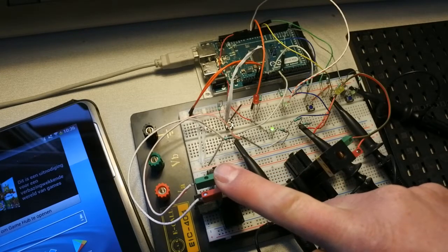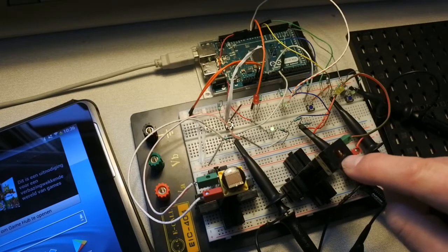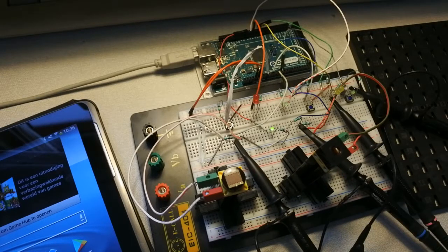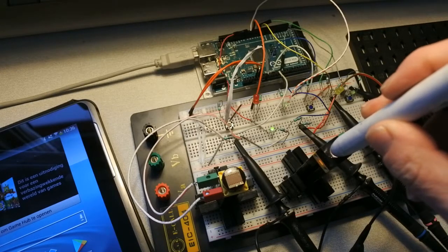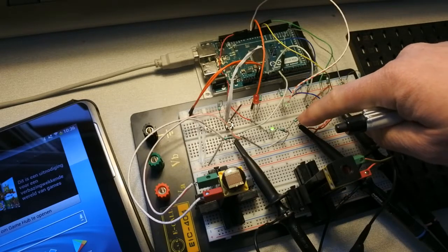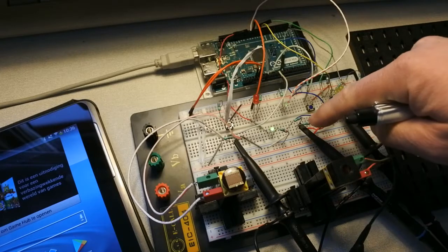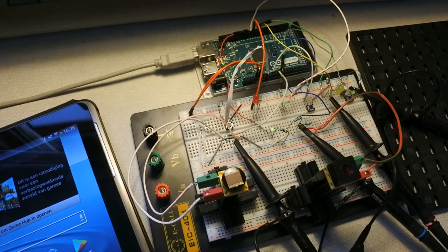So now there is full voltage. This is only giving voltage or passing voltage when there's light on it. So with this flashlight I shine and there is some voltage over it, which is led through this voltage divider. So the full 5 volts is not coming through. It is more like 2.5 volt. These are from fischertechnik.